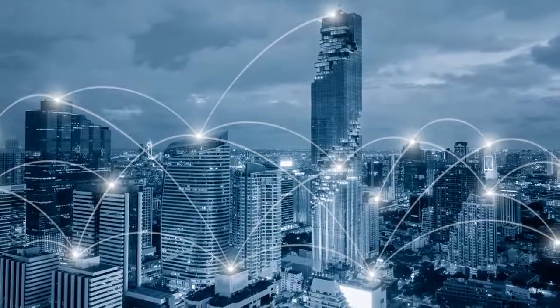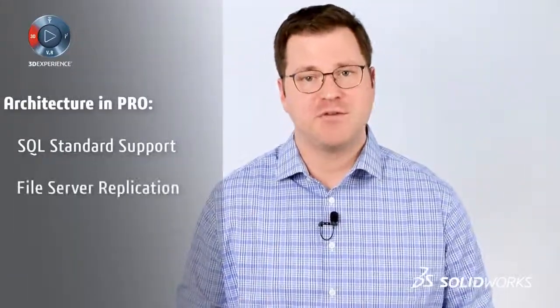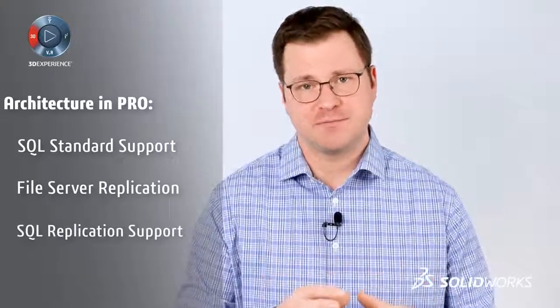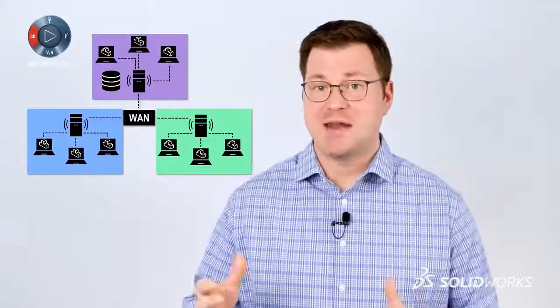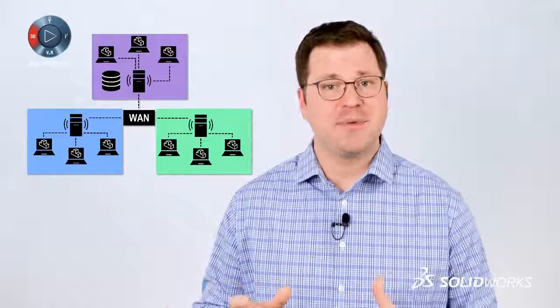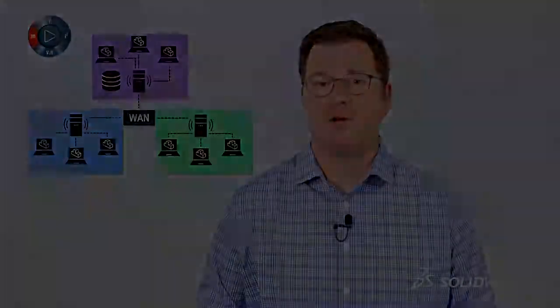As PDM installations grow and more teams start to leverage the tools, you're going to want to think about optimal software performance. Today's design teams are all over the globe, so how does each location access all the files and the product information? Well, even if two teams are working in different offices across the same campus, high network latency can be a bottleneck if everyone connects to the exact same PDM server. Replication is the answer here. Because a complete vault, files, and optionally the database can be regularly copied to each team's local server, replication offers an easy way to handle multi-site coordination challenges.